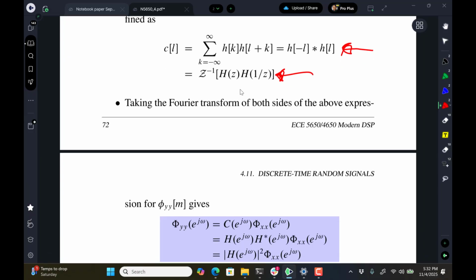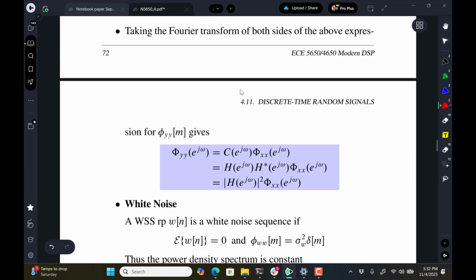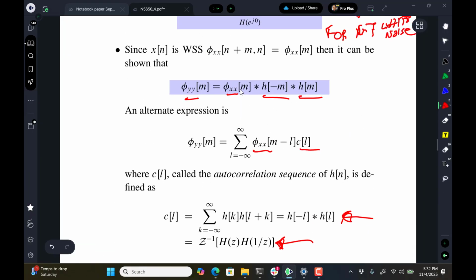So when we plug this stuff together and want to go to power spectral density, at the output that would involve all of this, and then the Fourier transform of those two convolutions, and then you'd be able to break those convolutions into the products of Fourier transforms of the three elements.